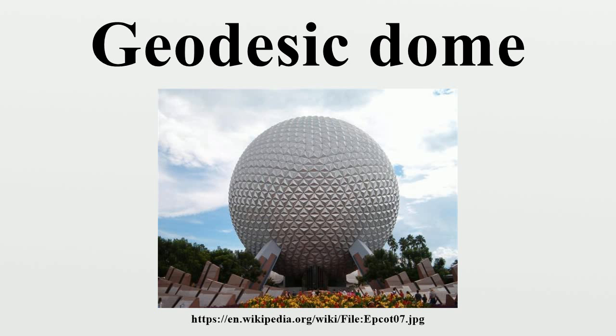This type of dome is often called a hub and strut dome because of the use of steel hubs to tie the struts together. Panelized domes are constructed of separately framed timbers covered in plywood. The three members comprising the triangular frame are often cut at compound angles in order to provide for a flat fitting of the various triangles. Holes are drilled through the members at precise locations and steel bolts then connect the triangles to form the dome. These members are often 2x4s or 2x6s, which allow for more insulation to fit within the triangle.